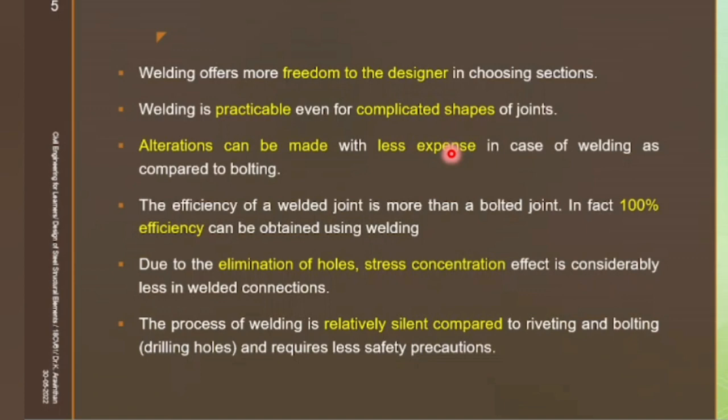You can remove that. The welding can be removed and you can use that as a new steel material. But if once you are making the holes in the connecting member and the member, you cannot use for another purpose. But in terms of weld, if you are dismantling the member, you can use it for whatever purpose it is required.